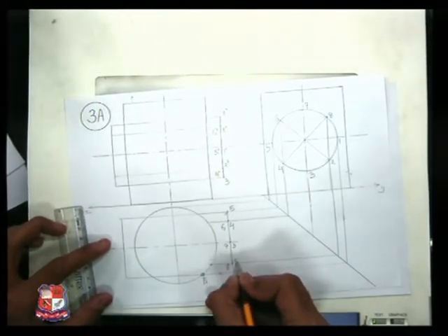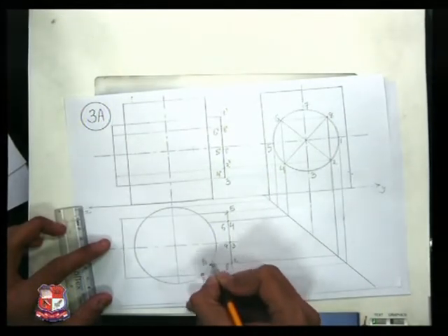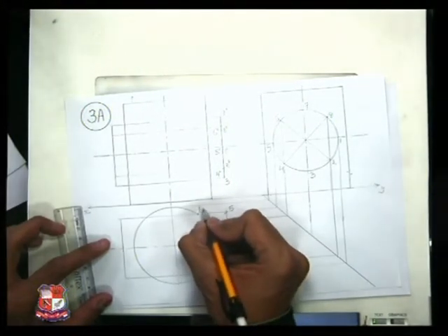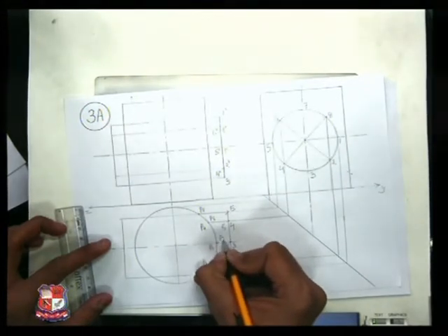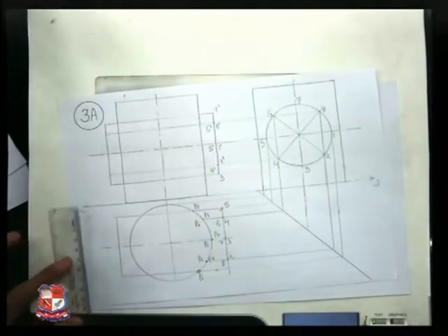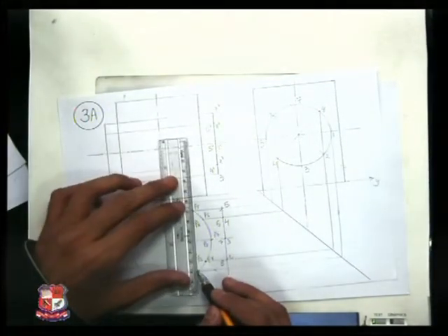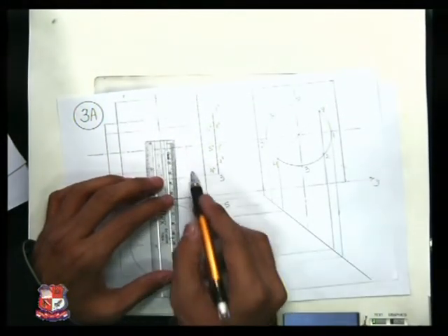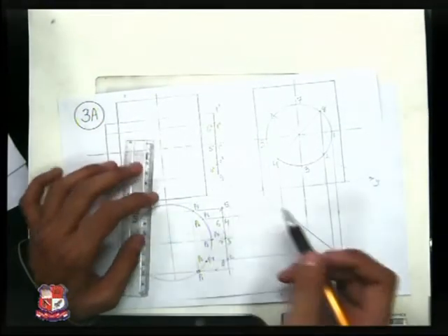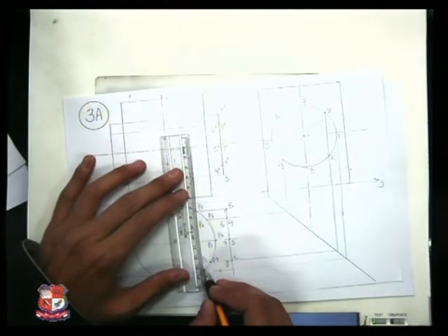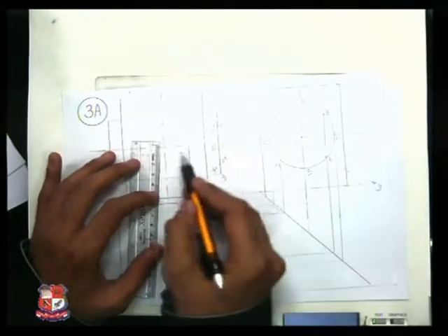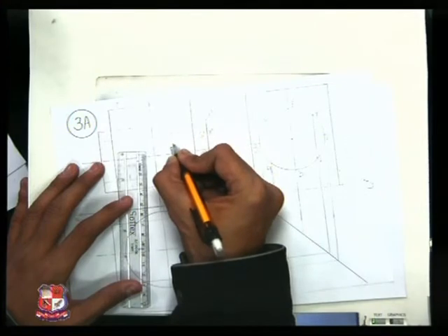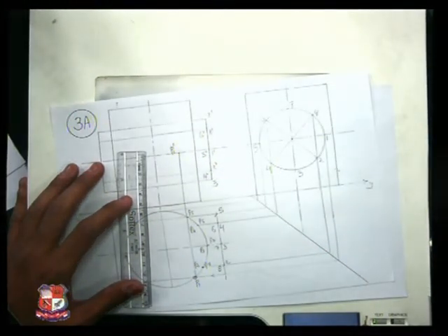Similarly, point 2 is here, so point number P2 would be here. Point number P3 is here, point number P4, and 5, so point number P5 would be there. Then P6, P7 and P8. Name all these points P1 to P8. Now from point P1, draw a straight vertical line as shown here, and one horizontal line from point 1. The intersection of these two lines, the vertical line from P1 and the horizontal line from point 1, is point number P1, or P1 dash, as it's a front view and the dash should be inserted.